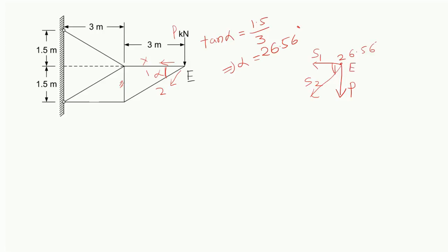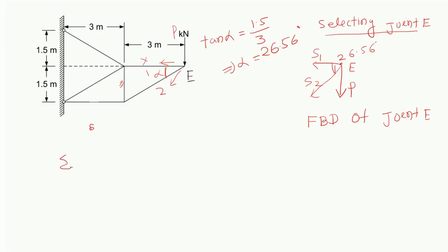So prior to that, you have to write everything in detail, just like selecting joint E. Below this diagram, you have to write out the free body diagram of joint E. Okay. So let's apply the equilibrium forces equation.